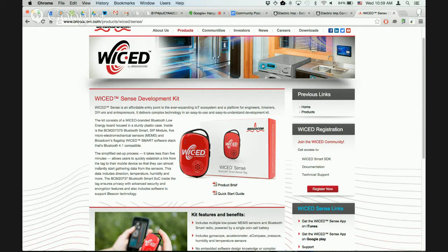The temperature data updates about once every second. If I ever get tired of talking to it, I can turn the notifications off by writing that client configuration descriptor in the SenseKit tag's GATT table, or I can just disconnect from it, at which point it'll go to sleep and stop advertising until somebody presses the button again in order to save power.